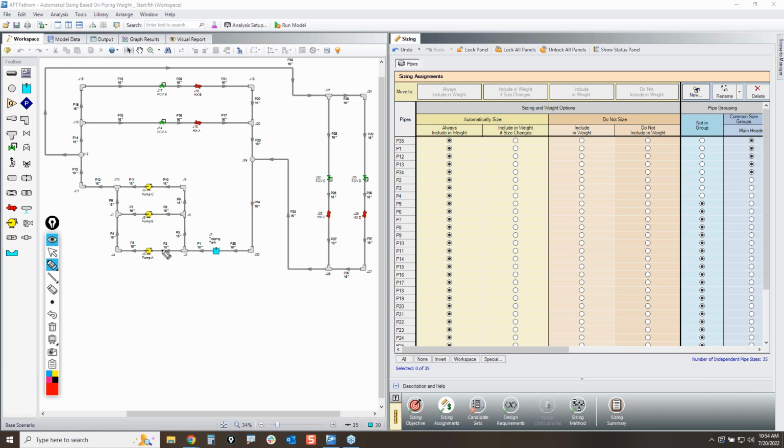So the pumps are not exactly going to be operating in the same fashion. They'll be off maybe by a little bit. So the sizes might be slightly different depending on how different of hydraulics I have. Maybe I've got additional valves. As you can see, I have an elbow here in each of these paths, but not in this path. Also, if you're setting these T's to detail to where you're accounting for their losses, that will change things as well. So that's why I might want to allow each different path to be slightly different.